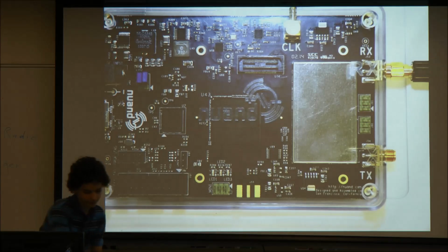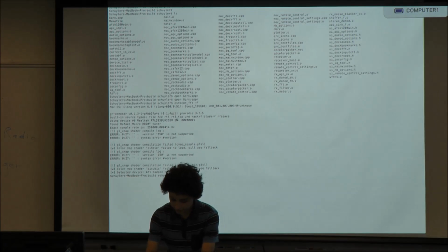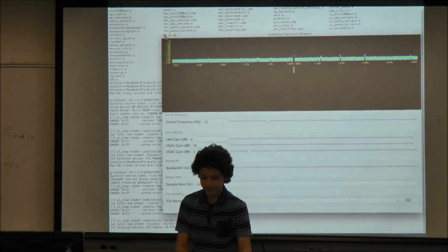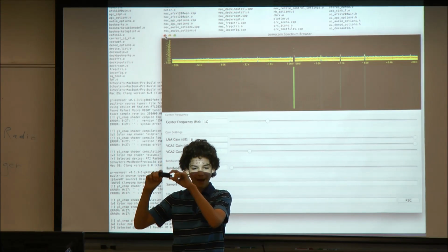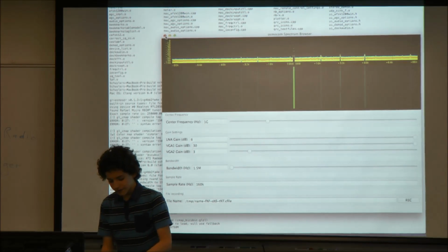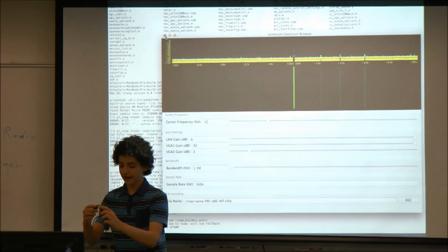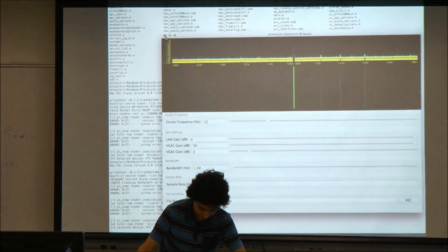So I'm going to switch back to my laptop. And if I connect the BladeRF and we do osmocom_fft -F, we could do -A, bladerf=0. This will run. Also, this dongle, depending on the version you get, is wider than the spacing between USB ports on a Mac. So it's really annoying if you want to have two devices in with two USB ports right next to each other. Get a USB extension cable and make sure it works. I have found some cheap ones that don't actually work entirely, but you can plug into the extension cable, plug the cable into your computer, and that will work too.